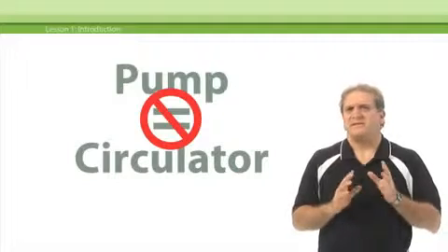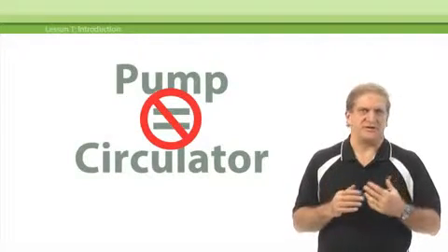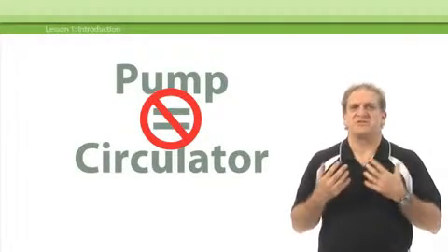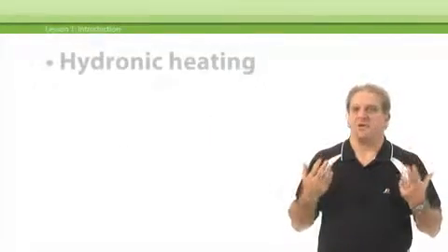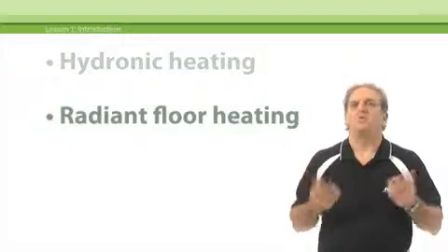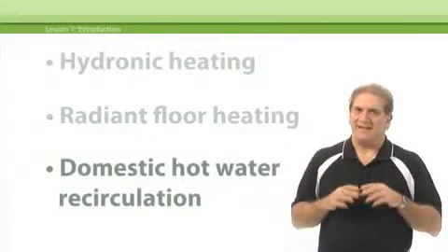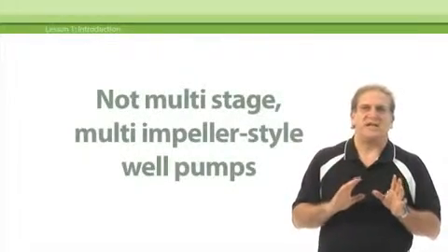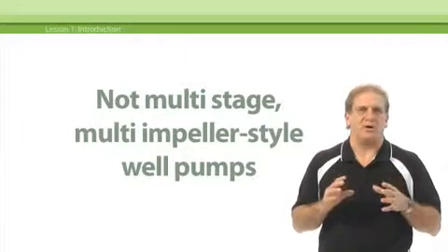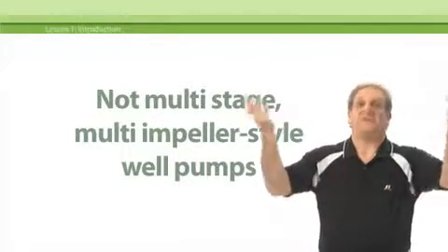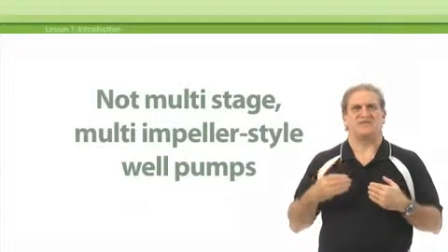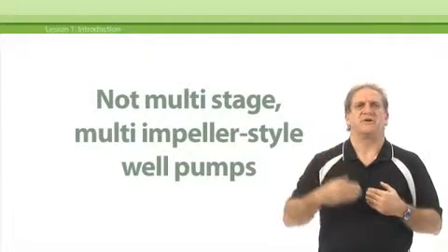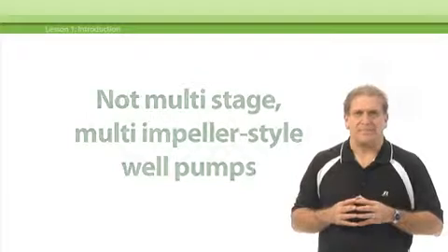It's important to make that distinction between a pump and a circulator, especially since we'll be discussing circulators that are used mainly in pressurized loop systems, systems like hydronic heating, radiant floor heating, or domestic hot water recirculation. Now, we're not talking about multi-stage, multi-impeller style well pumps designed to lift water a few hundred feet out of the ground. This is a distinction that makes a difference when sizing or selecting a circulator for your hydronic system, as we'll see later on.